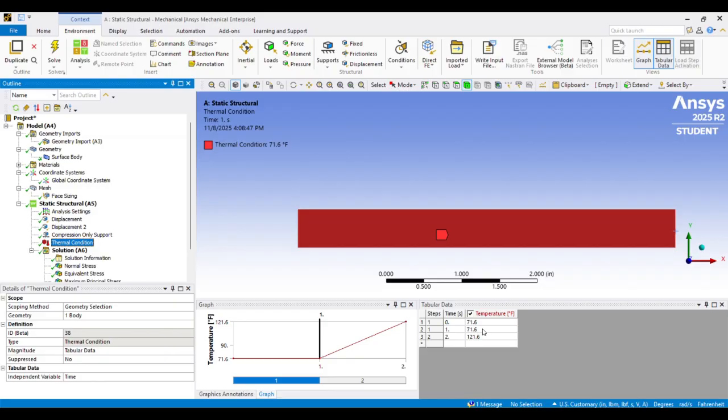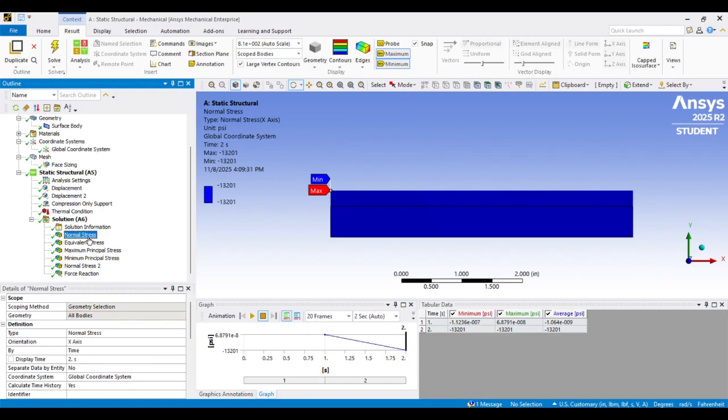One thing that I will mention is that in the previous video, I set 0 and 1 to 70. And I believe 0 needs to be kept at the reference temperature because that is referencing your coefficient of thermal expansion value. So to get my results to better match the hand calc, I had to leave that reference temperature. And then I set time step 1 equal to the reference temperature, and then added a 50-degree delta relative to the first time step. And then we post-processed our results.